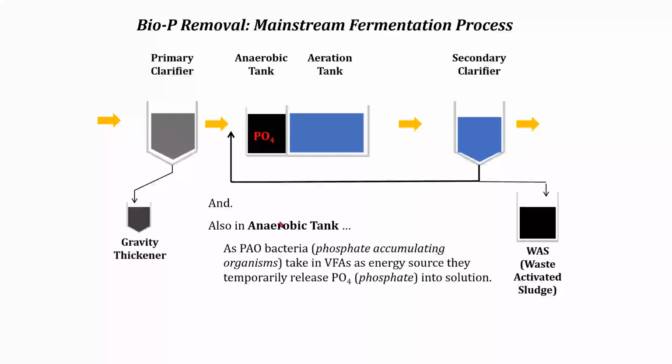So the soluble phosphorus leaving this tank that's operating just the way we want is going to be about 3 times the soluble phosphorus of the primary effluent or raw influent blended with the return sludge. 3 times. If it's only 2 times, it's not septic enough to get the full energizing that we want. If it's 4 times, it's too septic.